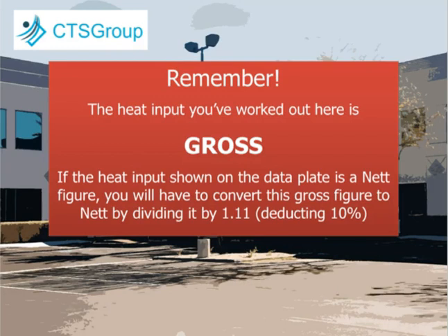Remember though, the heat input you've worked out here is gross. If the heat input shown on the data plate is a net figure, you'll have to convert this gross figure to a net figure by dividing by 1.11.